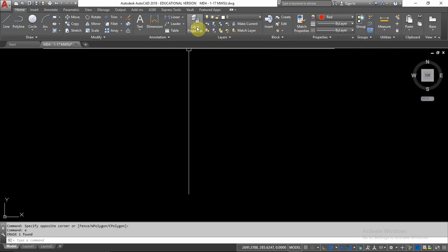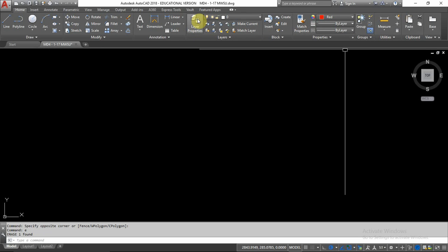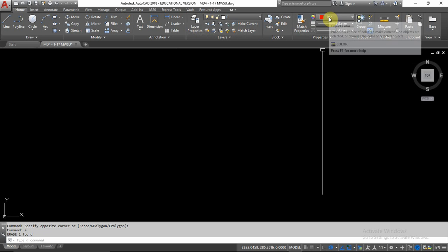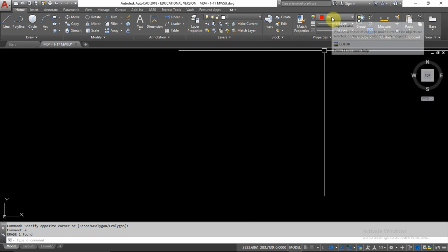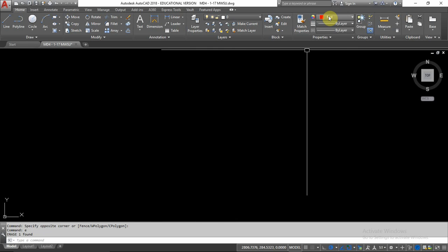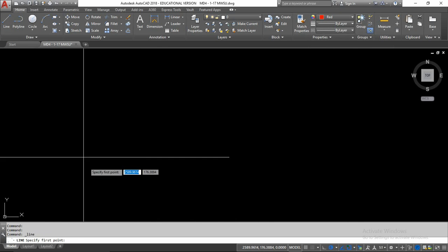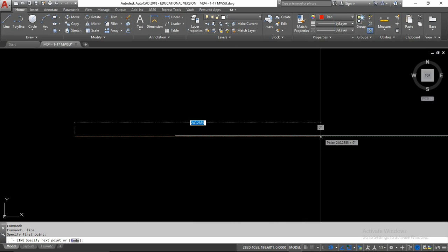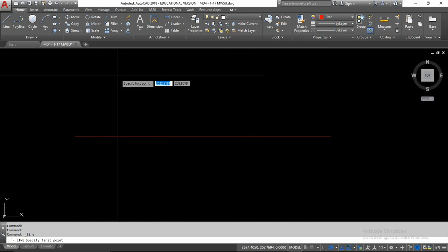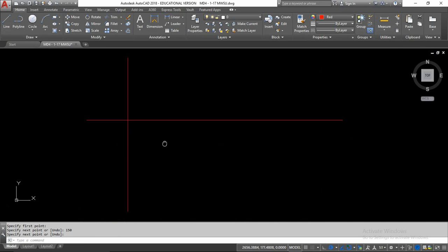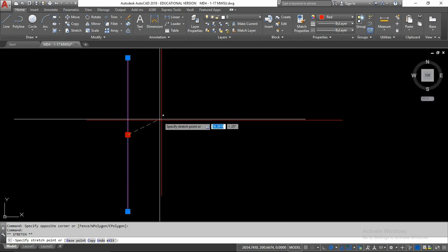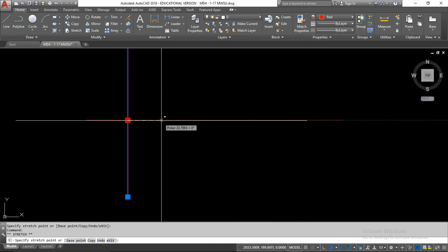That's because we're then going to use everything by layer, control our settings by layers. Now, the fact I've changed it now, I don't have anything created. I haven't selected anything. So therefore, whatever I create now is going to be the color red. So in this case, I will draw a line for about 240. I'm just going to go ahead and draw this at 250. Again, 120. I'll draw a vertical one at, I'm just kind of picking some random places, 150. Okay. I will go ahead and move this up here, and I'll move it down a little bit.